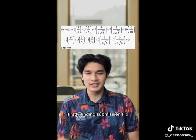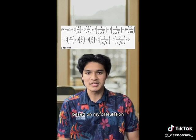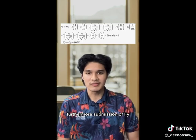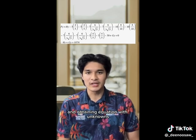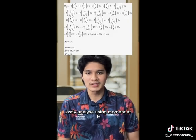Firstly, finding summation Fx, we need to list all the forces in the x-axis. Based on my calculation, I already listed them, and the final result obtained was Hx equal to 0. Furthermore, summation of Fy, same goes as x. I already listed all the forces acting on the y-axis and obtained an equation with unknowns Hx plus Gy equal to 107 Newton. Lastly, analyze using moment at H.